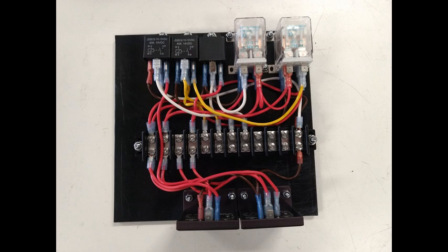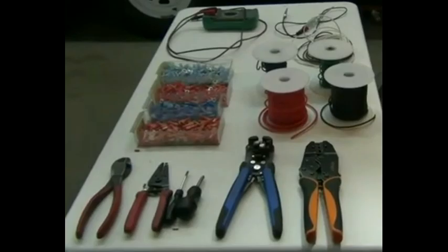Terminal strips aid in troubleshooting and make your setup more modular, which makes it easier to change or replace a component. There are a variety of different tools in the market for crimping cable lugs. Remember to use the right size of lug with the correct terminal hole size. Route the cable before crimping on the lugs to confirm the lug orientation on the cable, especially if you're using large wire or cable. They'll have an orientation to them because they'll come off of a spool.